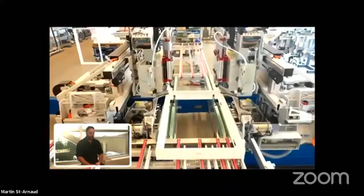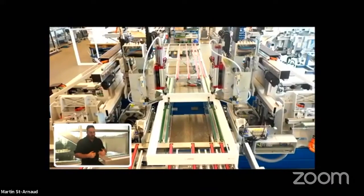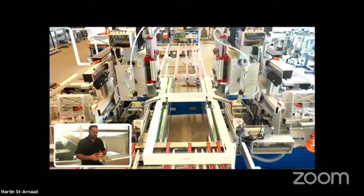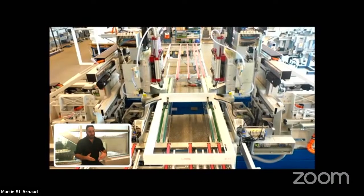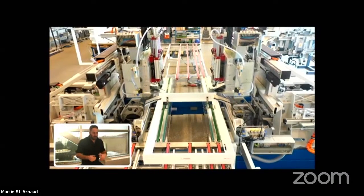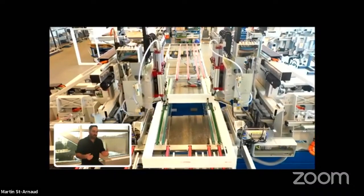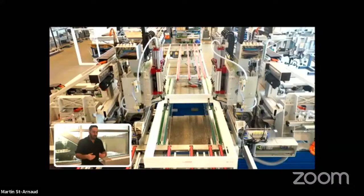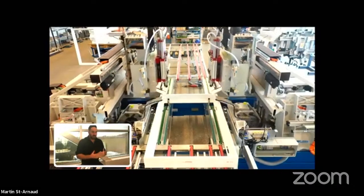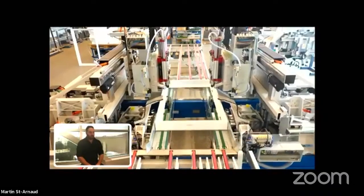So if I'm taking, again, my example of a 1,000 by 1,000 square, and for any good reason your welder is off, the part goes into your corner cleaner and it should be 1,000, but it's 999. Well, the corner cleaner is going to adjust itself to the right measurements and start its cleaning. So you're not going to have a clean that's going to be off the corner, instead of only giving the machine the information that it would be a 1,000 square. So those are things to, again, keep in mind.